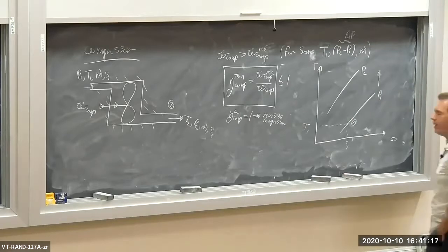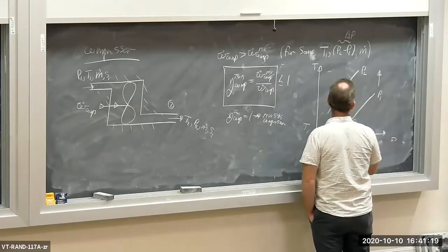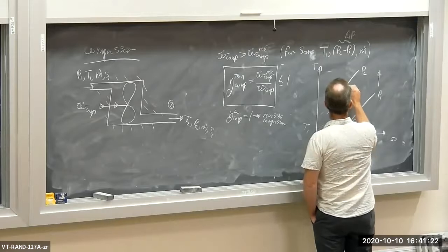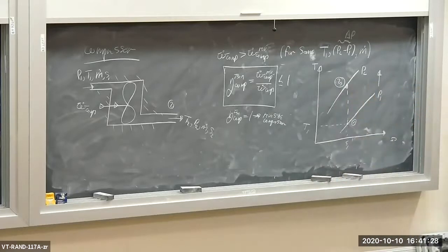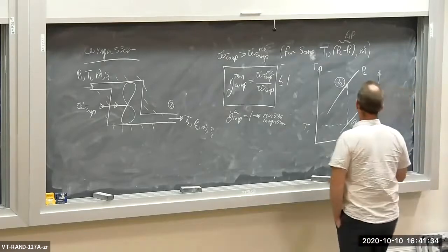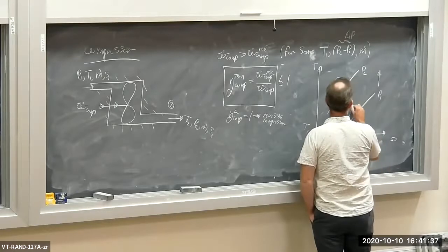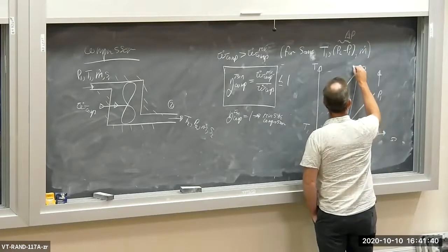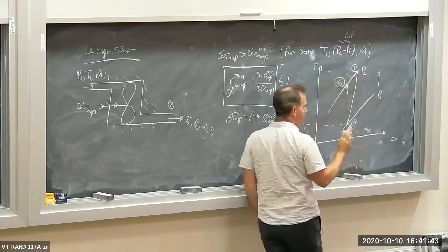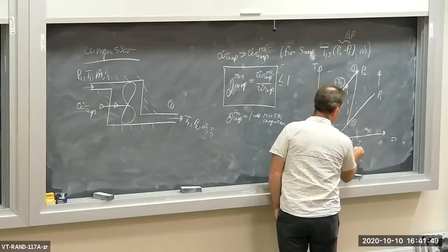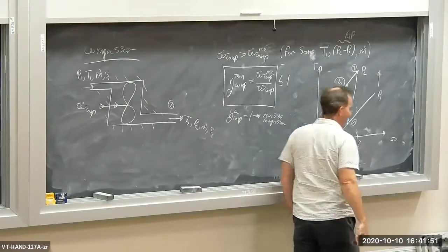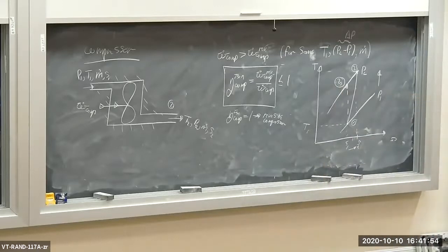The isentropic, that is, the least work consuming device, goes from 1 to 2s. That's the isentropic or reversible path. And the real device goes from 1 to 2. State 2 has a greater specific entropy than 1. So S2 is greater than S1 for the irreversible actual compressor.